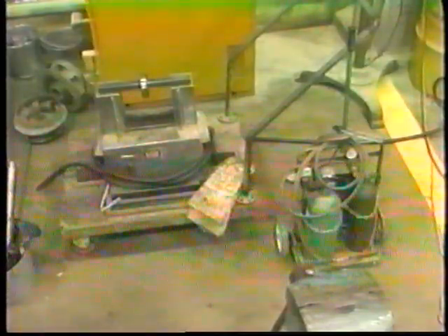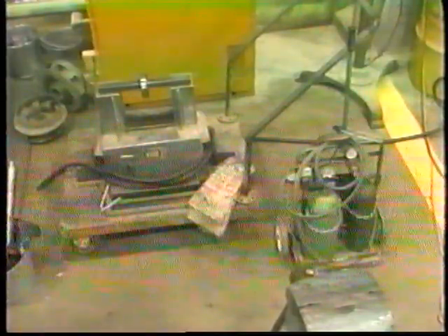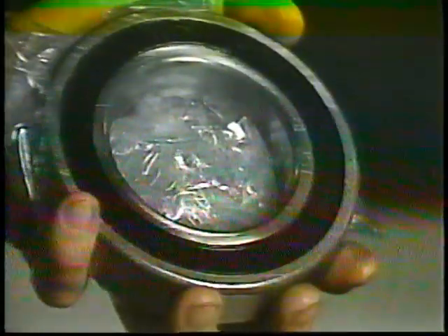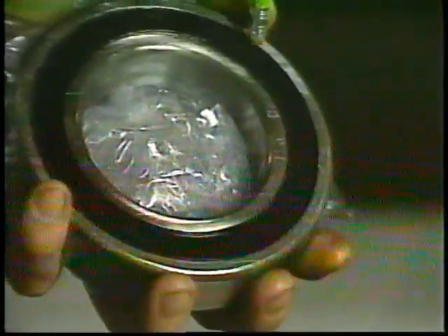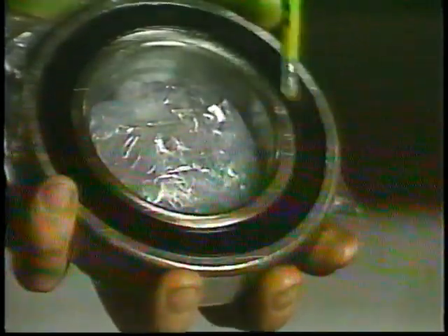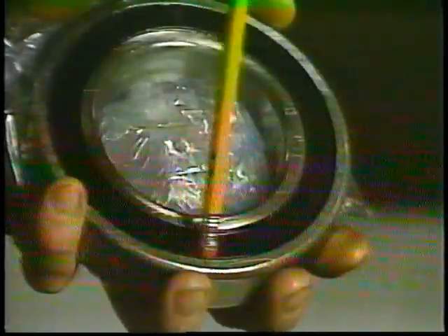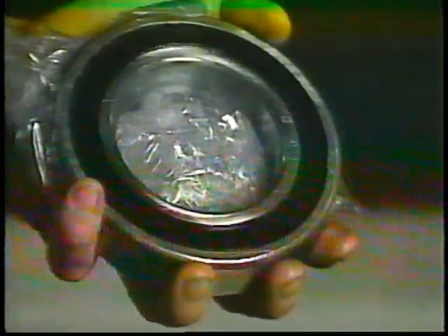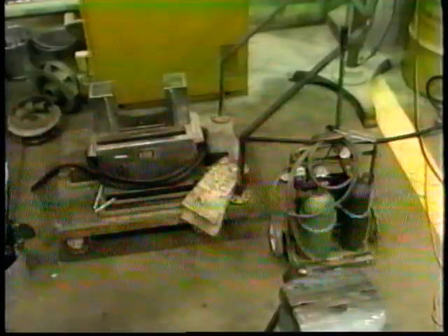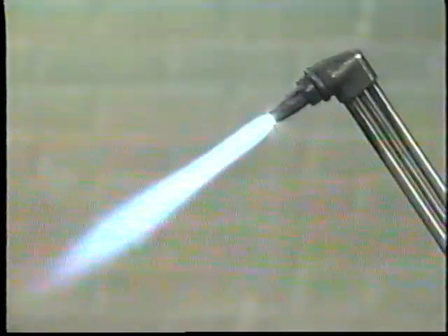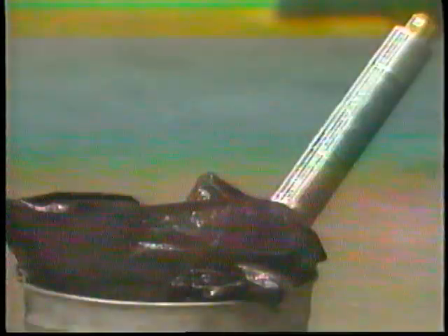The temperature should not exceed 230 degrees Fahrenheit. If the bearing has rubber or plastic seals, take extra care not to damage them through overheating. If it is permanently lubricated with grease, you should check the manufacturer's specifications. Never use a welding torch to heat a bearing. The concentrated heat can crack or warp the bearing, and it may permanently soften the metal.